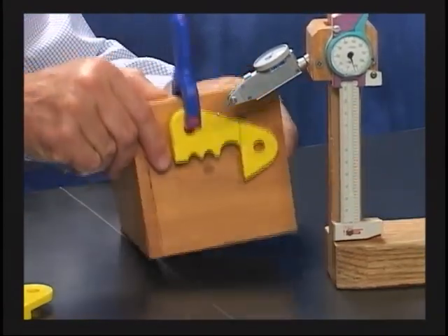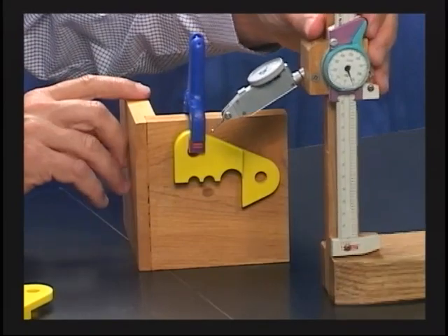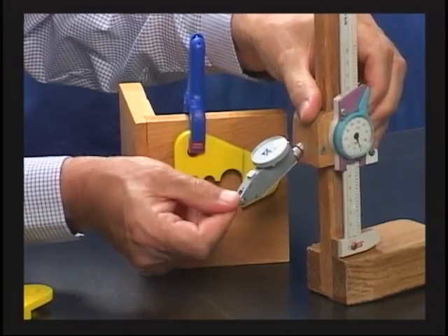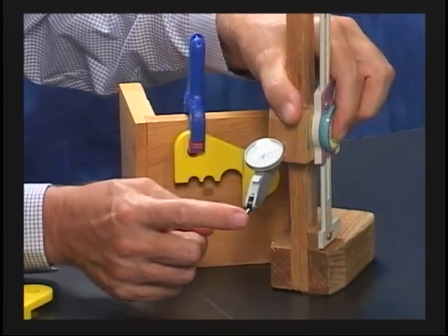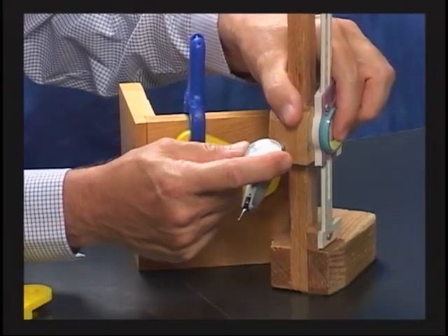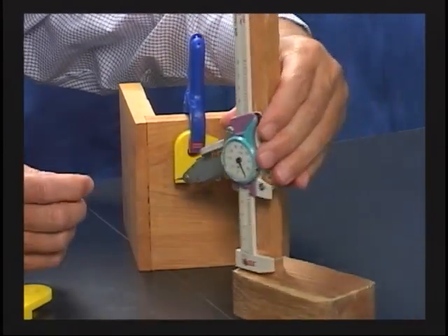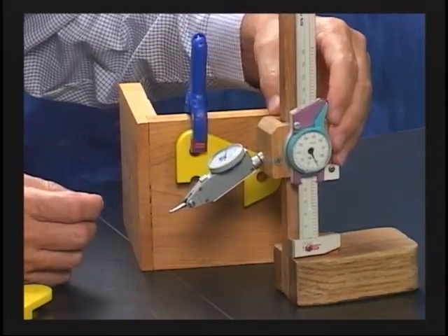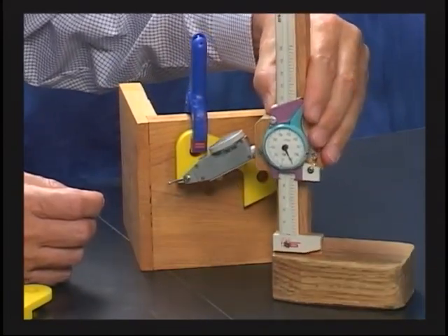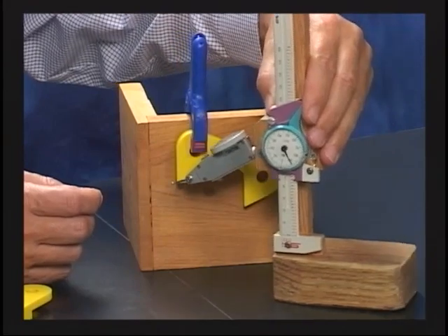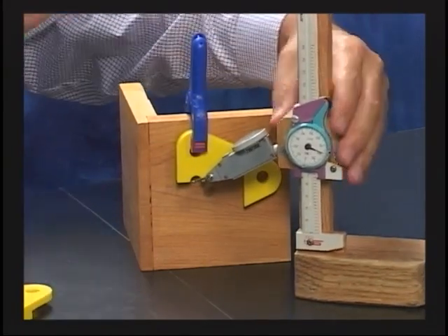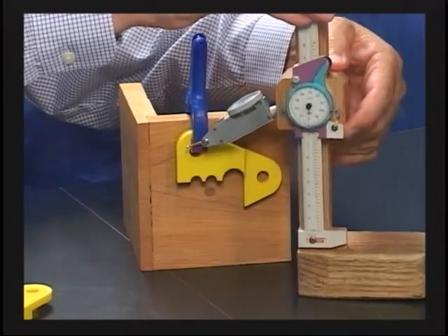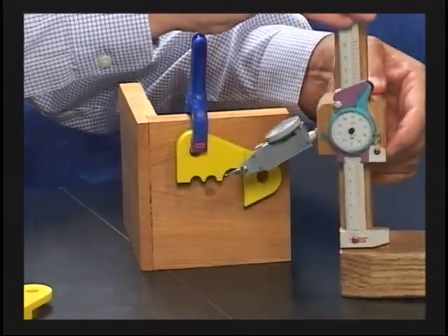And then to be able to measure in this direction, remember 90 degrees, I could come in and take my indicator, I have my needle. And this here is a dial test indicator. You notice as I push it down or I push it up, it gives me a reading. I can get where 0 is. I come in, get that bottom surface. And when I read about that bottom surface, what is it? That was the profile. All of those surfaces have to fall within that band of 5. All 3 of them have to fall within. Once I got that, I can make any measurements that I need to in this direction, right? I could go in and measure where the hole was. I could come in and measure points across here.